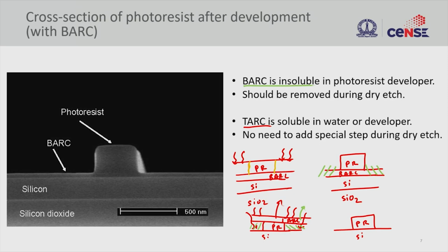But then if you are going to do lift off process, let us say, right. So, I am doing this lithography process in order to do lift off, right, for metal deposition and so on. In that instance, having BARC layer could be an issue. So, you may have to go to a BARC removal step separately and then come back for material deposition.